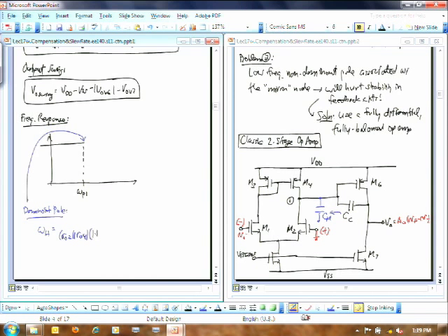Now I have a lot of nodes in this thing with a lot of other capacitors, but all these other nodes don't have nearly as much capacitance, and only one other node has a similar resistance, but it has much less capacitance than this one. So notice what I just did. I just neglected everything but this one and saved myself tons of time because I know this is the biggest time constant. There's an approximation you want to use. And you could do this on the exam too. You don't have to write out the rest of this. You can just say all the rest are negligible.